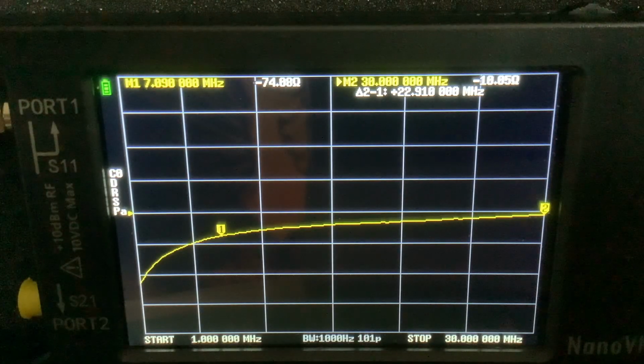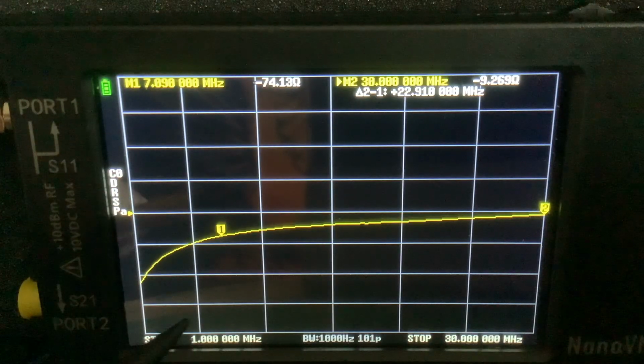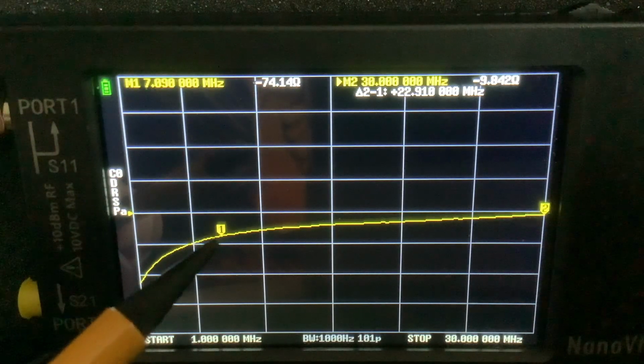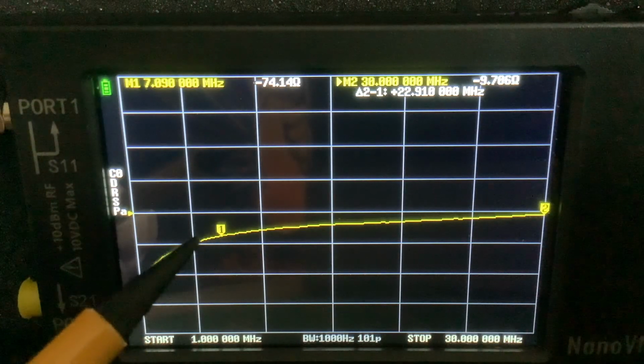And so you know this is going to present us with some challenges. First of all, in terms of impedance matching, because even if we manage to match the differing amounts of resistance on the input, if we're trying to build a broadband amplifier for the HF range, then obviously that's got some challenges, but we're really going to come against it when we try and deal with this reactance, because this reactance by its very nature varies with frequency.